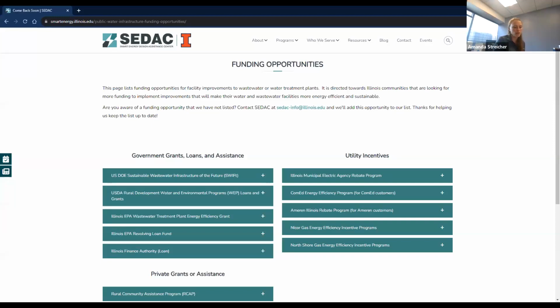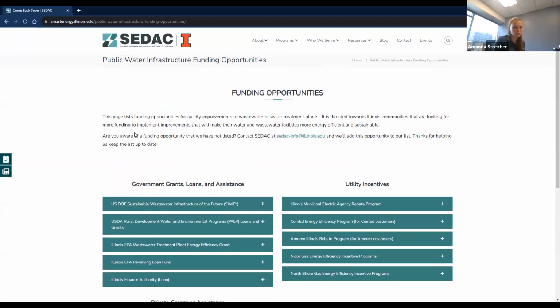But as we do that, selecting the correct equipment and looking at operation and maintenance costs, energy efficiency, polymer consumption, chemical consumption, all of those are key critical points for equipment selection that we talked about, and then analyzing that life cycle cost. That's where energy really comes into play. You're still going to spend energy when you're treating wastewater, but how much, and how we can efficiently and effectively select that equipment to reduce that is a big driver.